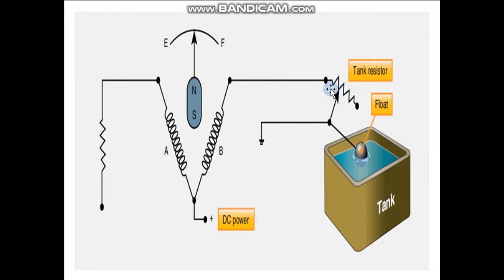This resistor is wired in series with one of the coils of the ratiometer type fuel gauge in the instrument panel. It changes the current flowing through the tank unit resistor. It changes the current flowing through the coil. This alters the magnetic field in which the indicating pointer pivots, and the calibrated dial indicates the corresponding fuel quantity.